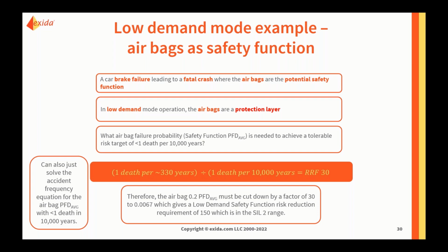most of the events or failures of my safety function are revealed by escalation, and the failure rate PFH term is a better description of the SIL performance of the device. But the standards have chosen to simplify this down to a 1-year cut point. If a safety function is demanded more than once a year, the standards call it high demand or continuous. And if the safety function is demanded less than once a year, the safety function is termed low demand in all of that. Now, thank you for those questions.